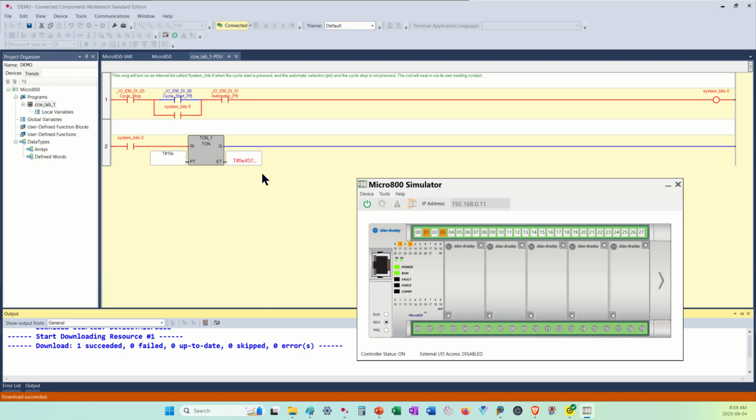Notice it does it in milliseconds, and notice how it seems to be jumping. It's not like you're seeing 9, 10, 11, 12. It's kind of jumping all over the place. The scan time on these processors is very, very fast. By the time the scan sends its information and it gets to the PC from the PLC, and Windows has had its time with it, you're looking, as far as the processor and process is concerned, at ancient history. Okay, so this is now set at 15 seconds.